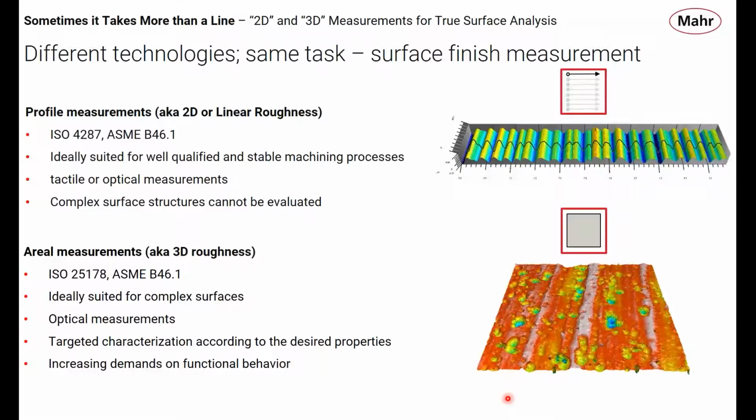This technique, these profile measurements are very, very well suited for well understood processes, well understood machining technologies. And what I mean by that in the concrete context is we know a process is stable, a process is well suited for profile measurements when we know we can monitor that RA value.